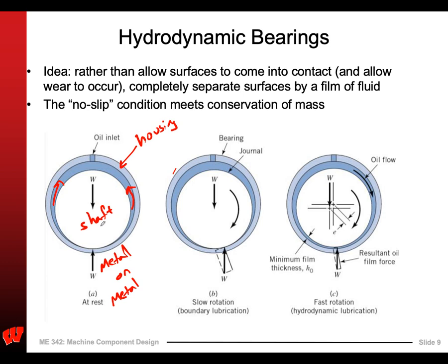Now, as soon as I start moving, what happens? This thing is moving, this thing's not moving. Remember in fluid mechanics, we called this Couette flow, a shear-driven flow. But there's this heavy weight here, so there's a high pressure here. Boy, this could begin to look like a fluids problem, where I have shear driving the flow this way, pressure pushing the fluid back this way, and which wins? That's the whole point of Navier-Stokes, it's a balance between pressure forces, shear forces, gravitational forces, etc.